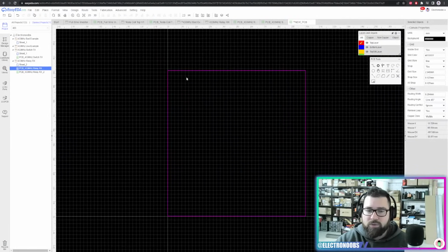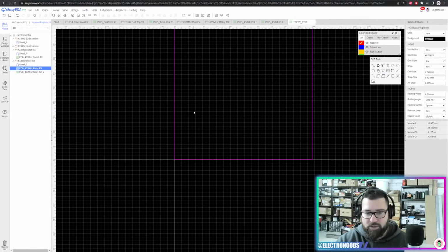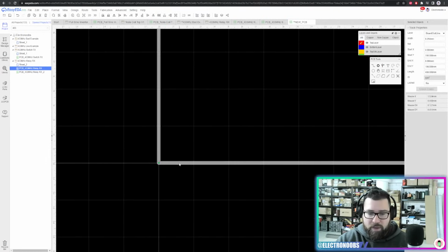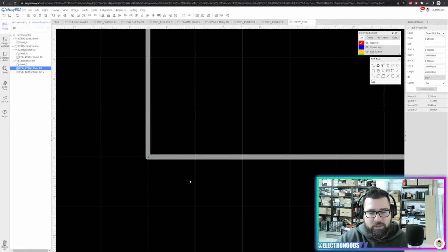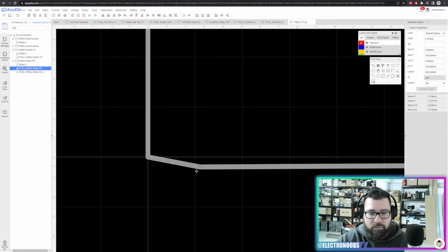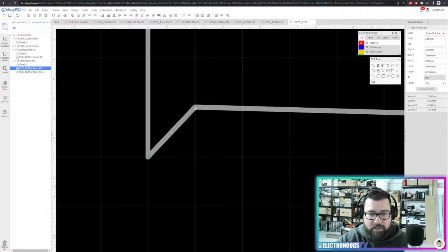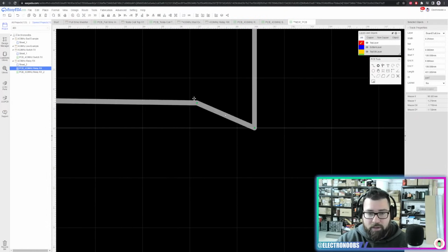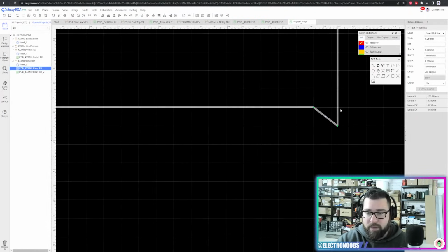If you want to make an original shape for your PCB, if you go close to the outline and make just one click, it will turn white. Then when it's white, you make a double click, and you will add another point, and you can move this point all around. So for example, you can place it here, and then make another point and place it here, and you can play with the size of the grid.